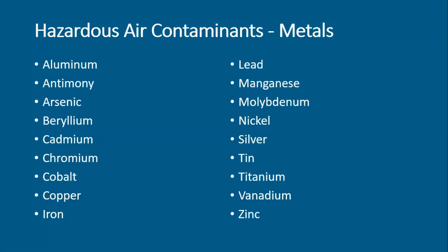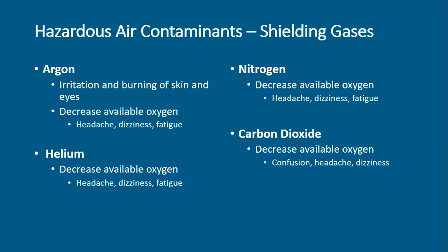Metals and gases can both be sources of air contaminants when heated or used during the welding process. Shielding gases can also be sources of air contaminants. It is important for employers and employees to not only be aware of the gases used as fuels, but also those used for shielding. The following are general hazards related to exposures to the contents of some shielding gases.